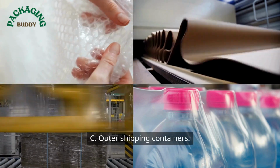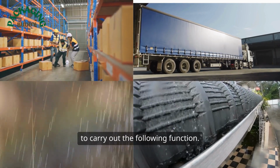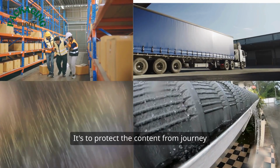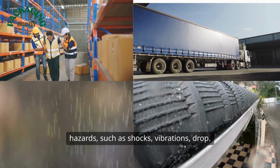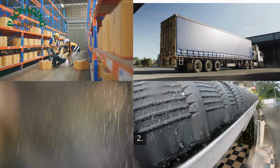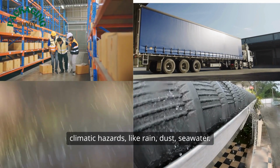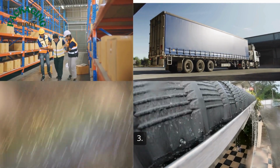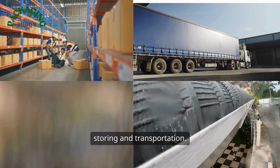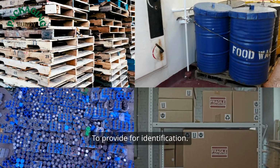C. Outer shipping containers. Shipping containers are supposed to carry out the following functions. 1. To protect the content from journey hazards, such as shocks, vibrations, drops. 2. Climatic hazards, like rain, dust, seawater. 3. To provide easy handling, storing, and transportation. 4. To provide for identification.